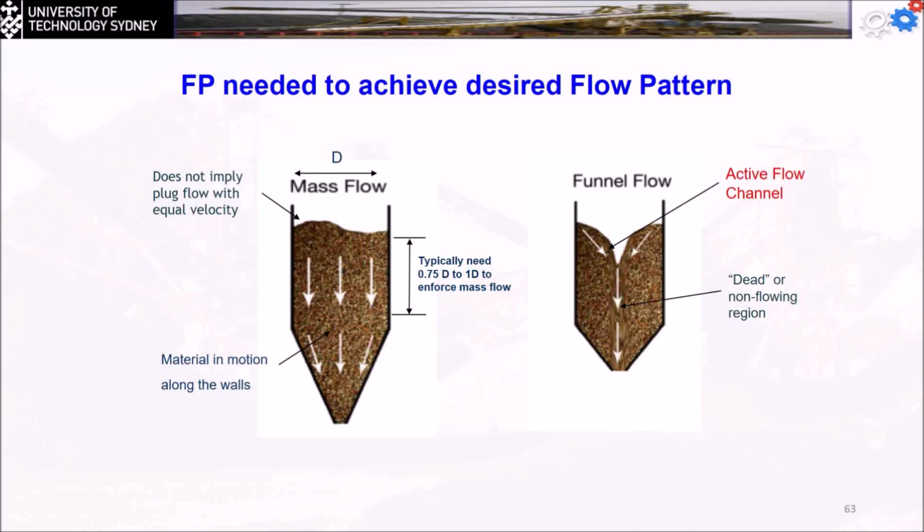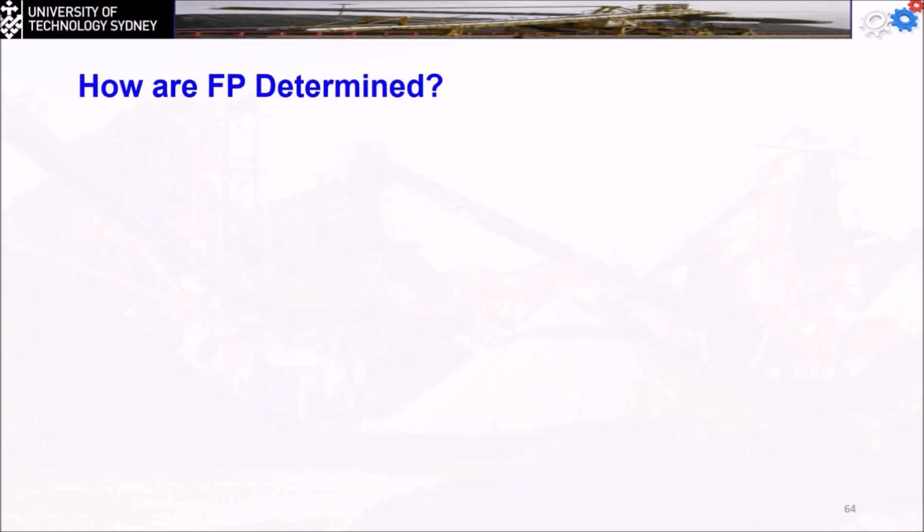So other than the mechanical flaws that might prevent a proper flow, what other factors could contribute to this? Okay, the cohesion, when you leave it for a longer time, because the material is going to build up together. Well, as we mentioned once again, the moisture content and the compressibility. We don't want the material to be compressed, so we take a smaller size, because if you compress something, you're going to find a problem taking it out.